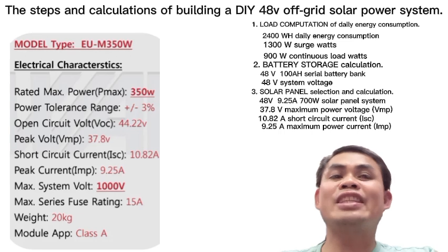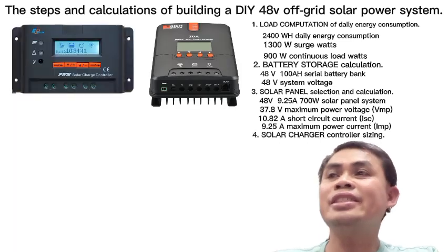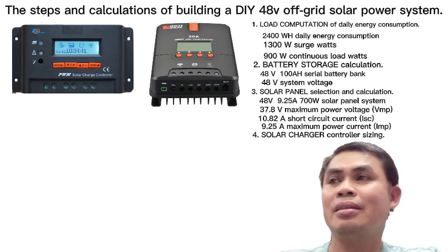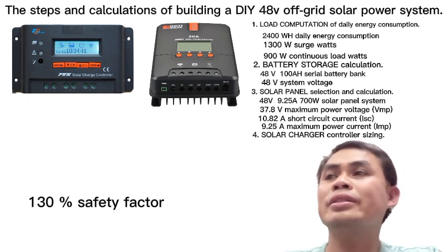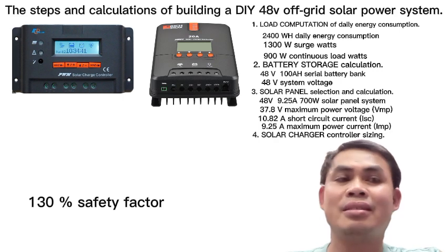We are now in step 4, solar charge controller sizing. We have 130% as a safety factor, since our solar panel's maximum watts will rise during sunny days.